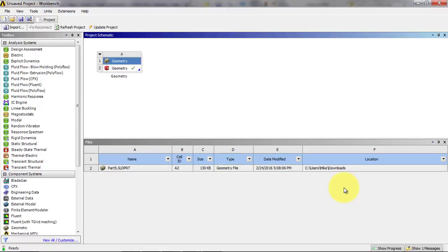This is where we add things or connect things where we want things to happen. What it did was load the geometry into this plain old geometry box. So it's not going to do any analysis with this as it's shown. It's just straight up geometry by itself. So we need to tell it what kind of analysis we want to do. For this one, because we're going to be loading with pressure and looking at the overall structural analysis, this is a static structural analysis.